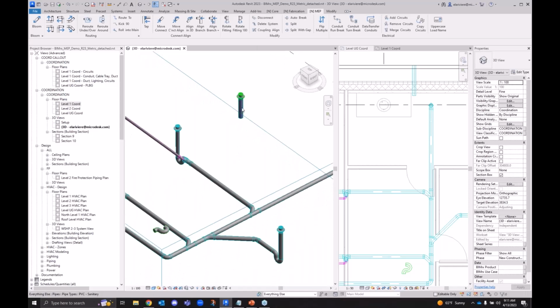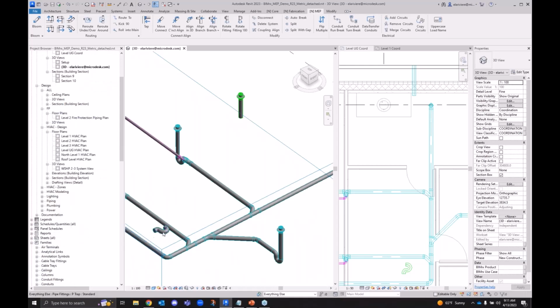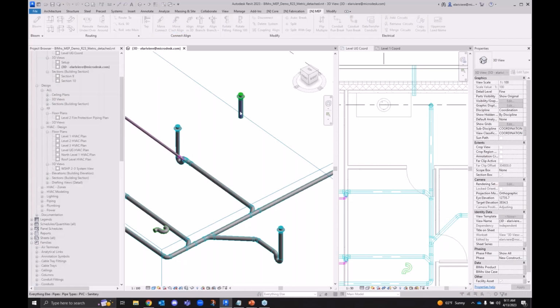Revit. So we've done a bloom and that's given us an extension. I have a P-trap that I already placed that came in from my families browser. For some reason, every P-trap was built sideways. Mine is no different. Here it is. If we want to make that connection over here, beyond move connect, we can use this move connect align, which is going to let me choose a stationary and then click the connector I want.